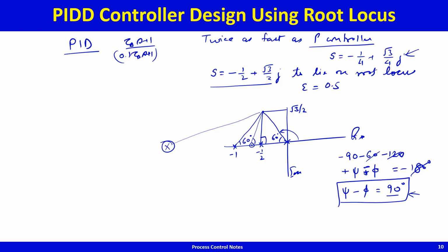Now if I start putting my 0 over here, I am contributing a more than 90 degree angle because of the 0. But if this guy is 10 times the distance, you see this angle is also increasing. As the 0 is moving this way, the pole is also moving this way, because the pole is only 10 times the distance away.